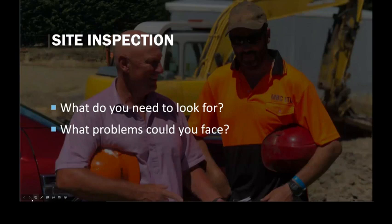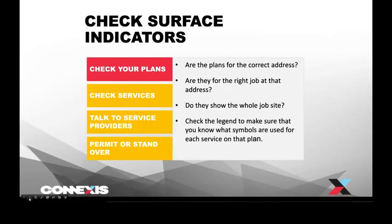All right. So here's a few things to consider. So you've got to go and do this drain laying job. First thing, check the plans if you've got them. If you're doing a new job, you would have consented plans. So you need to make sure that they are consented. They're not just draft plans, and that they've got all the right information on them. So it's got the right address, it's the right job, so you're not turning up with the plans for next door.